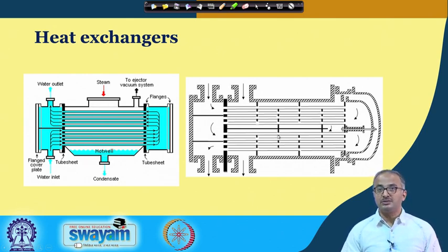And here in this configuration, you can see that the tube side fluid is going from here. It is first going like this, first pass, then it is taking a U-turn, this second pass, then taking a third turn, it's a third pass, and then it's going like this, it's a fourth pass. So, there are four passes on the tube side.